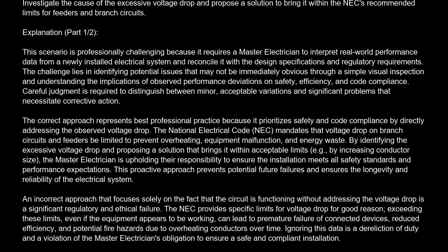An incorrect approach that focuses solely on the fact that the circuit is functioning without addressing the voltage drop is a significant regulatory and ethical failure. The NEC provides specific limits for voltage drop for good reason. Exceeding these limits, even if the equipment appears to be working, can lead to premature failure of connected devices, reduced efficiency, and potential fire hazards due to overheating conductors over time. Ignoring this data is a dereliction of duty and a violation of the master electrician's obligation to ensure a safe